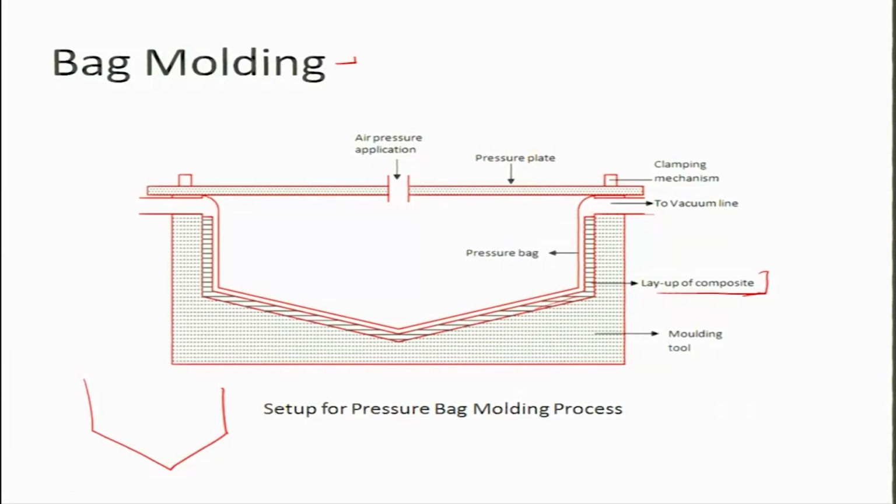So, this is my pressure bag, okay, and what that means is the bag should have the same shape as the inside surface of the part. So, if I want to change the part, I have to change this pressure bag, and from here I apply extra pressure. So, I can put 20-30 atmospheres of pressure, and of course, when this pressure is there, this presses uniformly.